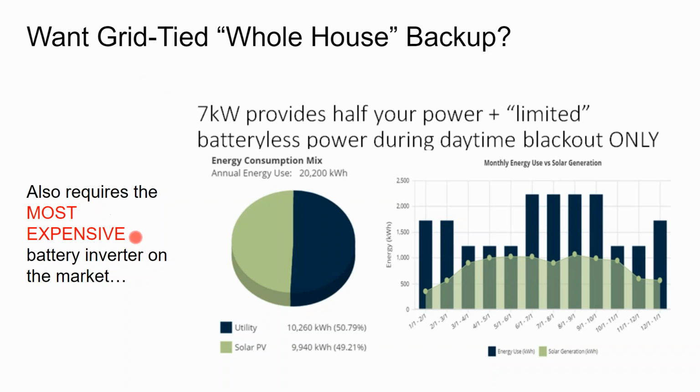And then on top of that, these grid-tied battery inverters are the most expensive inverter on the market, because not only do they have to take the power from the solar array and squirt it out onto the grid, but now they need to take power from the grid and suck it into the battery. So it's two directions, not just one: solar out and then grid in to charge the battery.